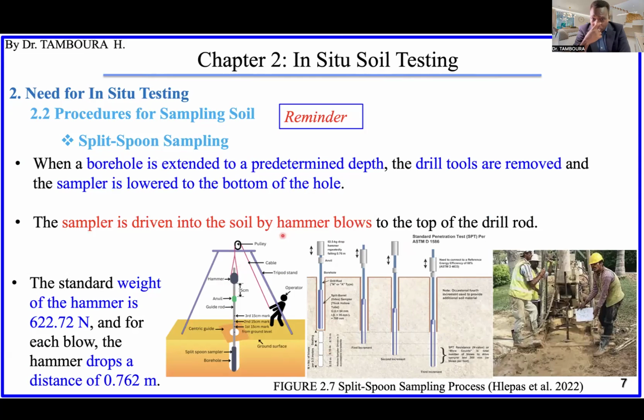So it was said that after doing the borehole like this one, for example, we load the SPT sampler at the bottom of the borehole, and then we start driving this sampler into the soil using the hammer, okay, by hammer blows.